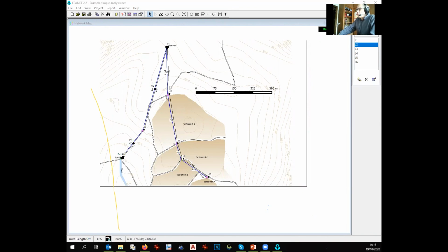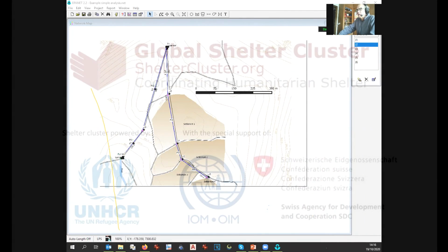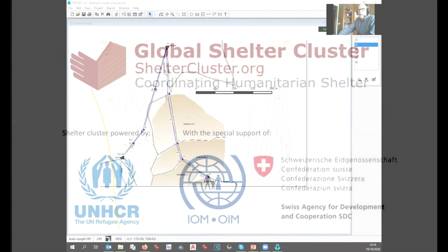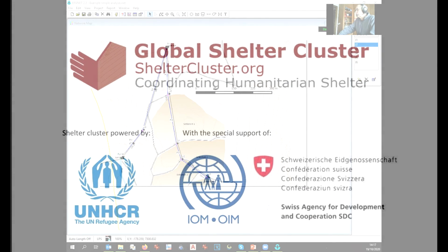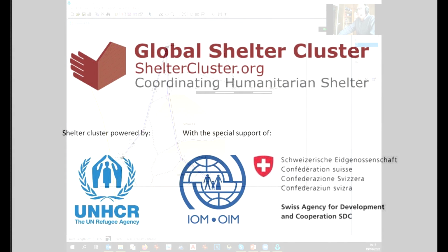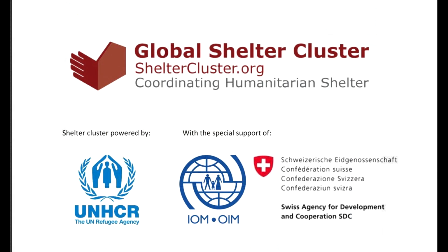Not designed, but we will do the simulation over time next week, and then the system will tell you if with your parameters the simulation over time works well or not. And if it doesn't work, it will tell you it doesn't work because the tank is too small, for example, because you see it's going to be empty. So it means you are demanding too much water from your tank. So either you pump more hours or you make a bigger tank. Then you change the parameter and you run the simulation again. And then you have to fine tune your system until it works properly.